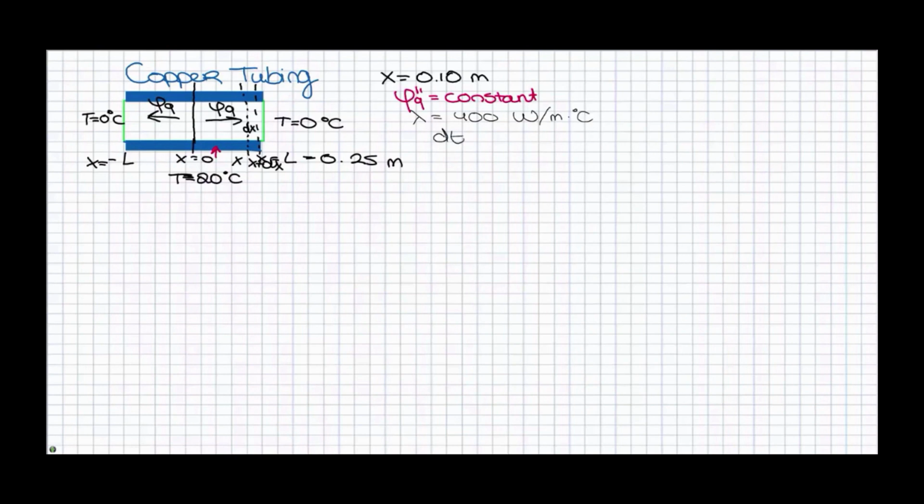So now you can set up the energy balance. The energy balance has to be set up over the small part dx where the heat is transferring through the surface and heat is produced, which gives the following equation. The energy balance equals 0 because the situation is stationary. This means that the heat flux in and the heat flux out are the same. So the heat flux overall is constant, which was already given.